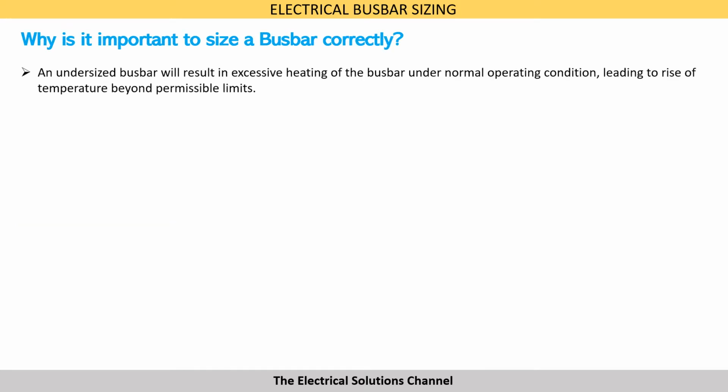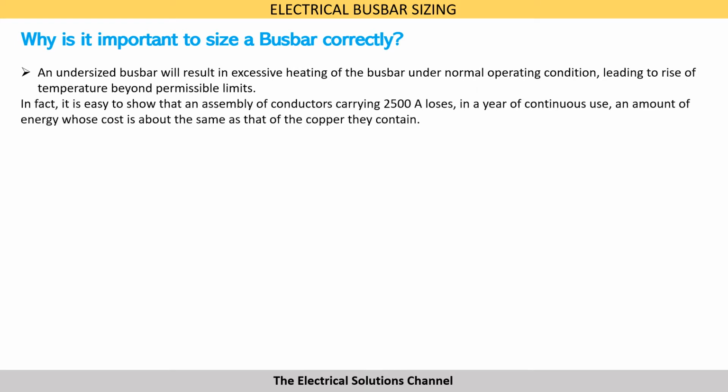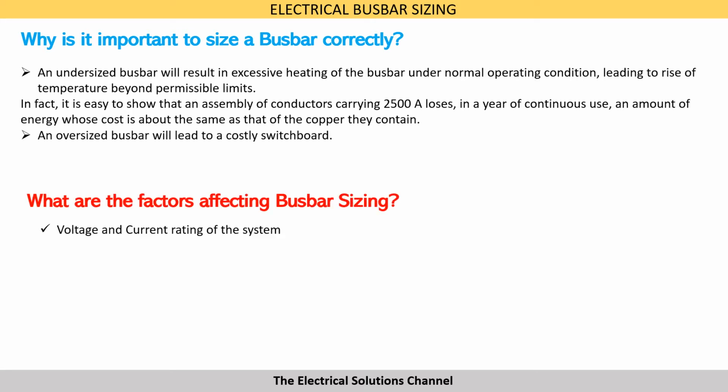Now let us understand why it is important to size a busbar correctly. Well, an undersized busbar will result in excessive heating of the busbar under normal operating conditions, leading to a rise of temperature beyond permissible limits, while an oversized busbar will lead to a costly switchboard.